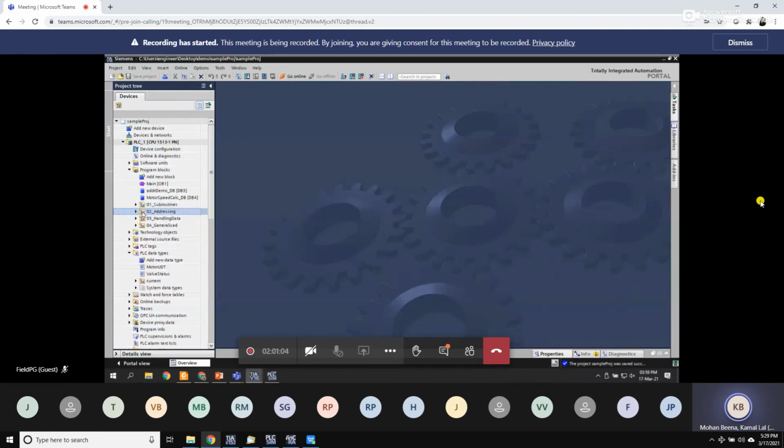Now, we said as per the recommendation, it is always better to use symbolic addressing because the hardware platform itself is really optimized to handle that. We still have that old type of addressing available, but know this, that is still available just for backward compatibility purposes. So if you have a new project, try your level best to stick with symbolic addressing.